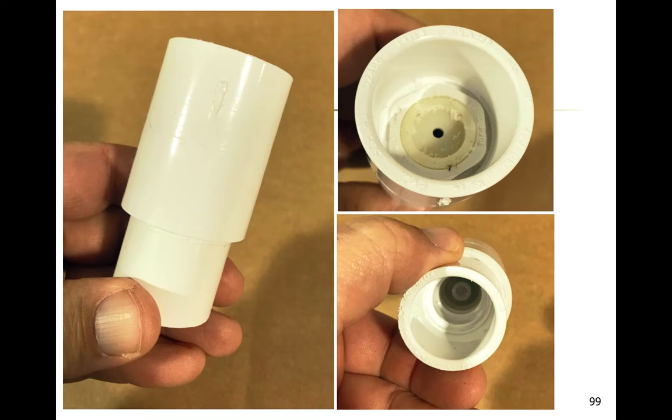The cold weather adapter has a small diaphragm in there that when the pump turns on and pressurizes, it seals up that small hole, and then when the pump shuts off and the pressure is released, that diaphragm relaxes again and allows a small amount of water to leave between doses. So what that'll do is preclude the water, if it does freeze, from expanding beyond the capability of the plumbing. At least half of the internal part of the headworks will drain between doses. So even if it were to freeze, it won't break any of the pipes.